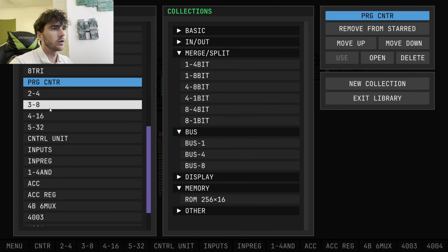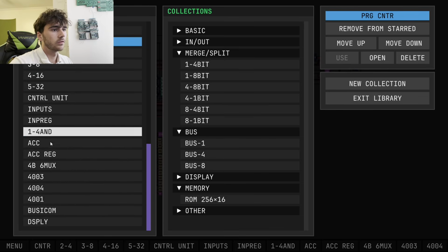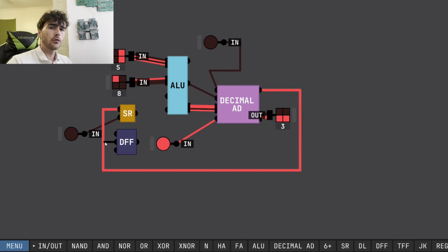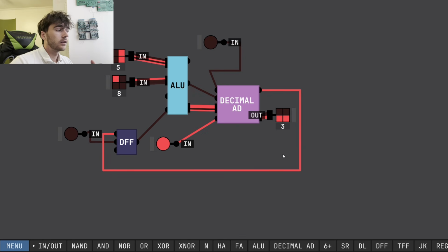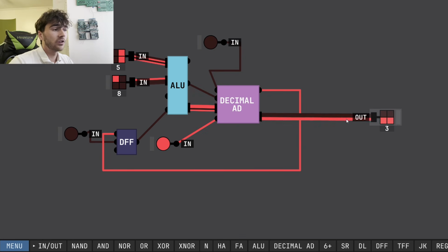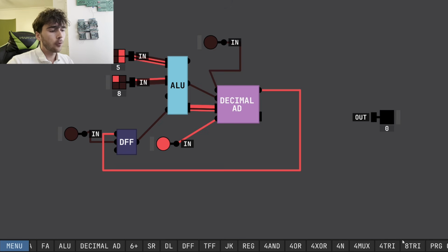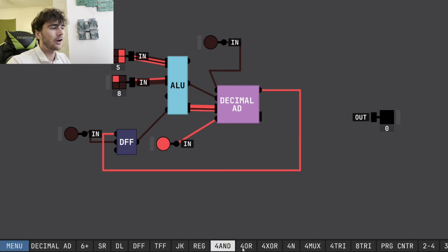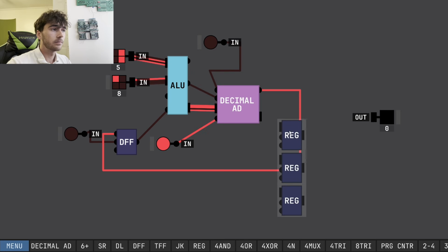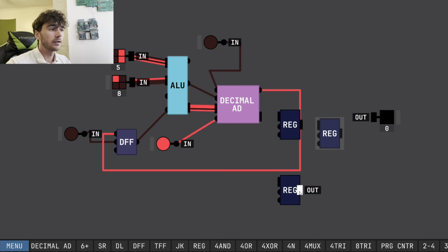And now let's go to our ALU, wherever it is. So the 4004 kind of added numbers a little bit differently. A normal computer would just add the binary numbers together, but this was used for calculators, so it was heavily designed towards a calculator. A 4-bit number can represent numbers from 0 to 15, and in decimal, all the numbers we really care about are 0 to 9. So each 4-bit number is going to represent a place value of our base 10 system in a calculation.